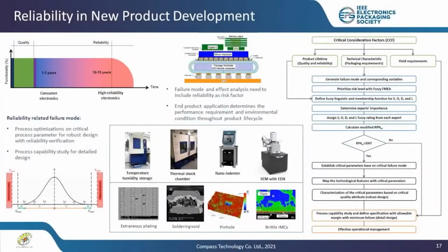To improve the reliability performance of flexible electronics, there are a couple of areas we always need to stay focused on. First is the technical characteristic, as the packaging configuration is getting more and more complex, and the IC is stacked with heterogeneous integration. We should expect to see a new class of failure mode induced by any fine pitch interconnect or any interface caused by thermal mismatch, causing long-term reliability issues. So understanding the physics of failure between each process, and the mechanism behind each failure mode, becomes very important in order to predict and improve the product reliability performance.